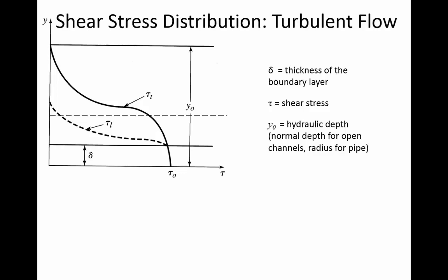velocity is high. So in other words, if we look at the cross-section here on the screen, if the water is moving slowly, then maybe the shear stress is pretty high in this shaded region, but on the inside there's not much shear stress, and so the water is moving without too much resistance when the velocity is low. When the velocity is low, the shear stress isn't reaching out into the flow field as much.